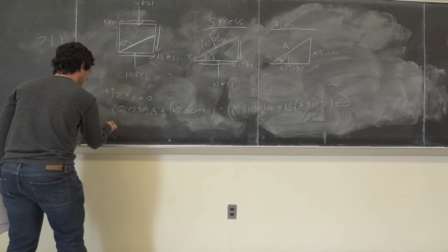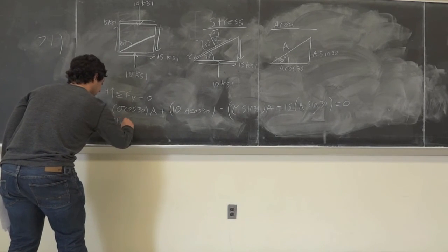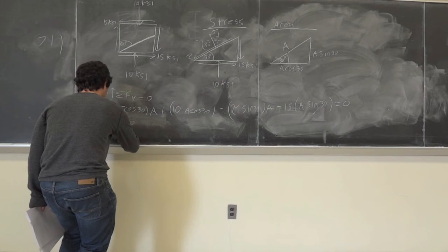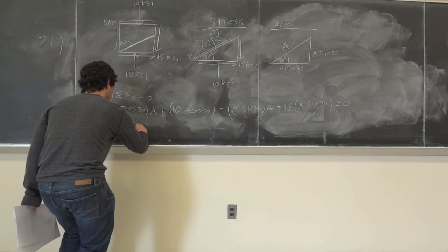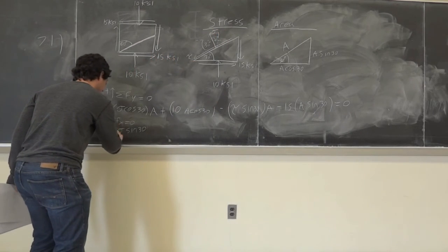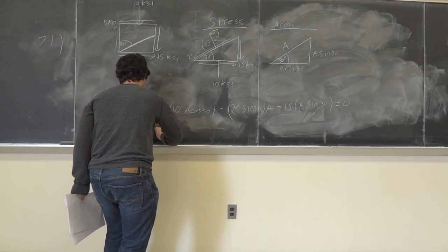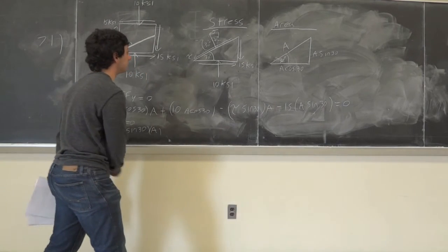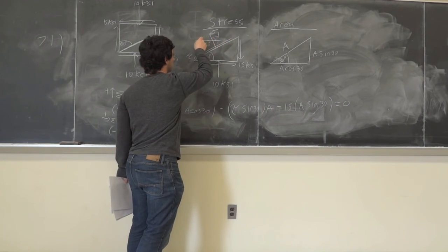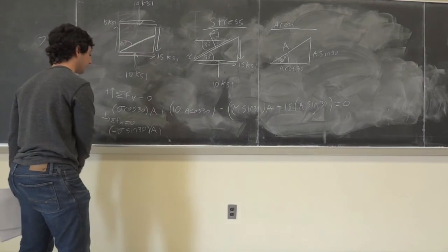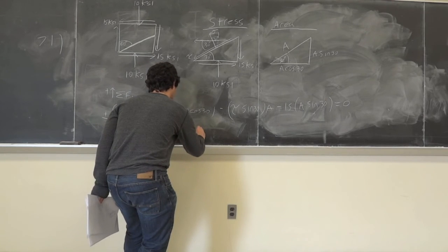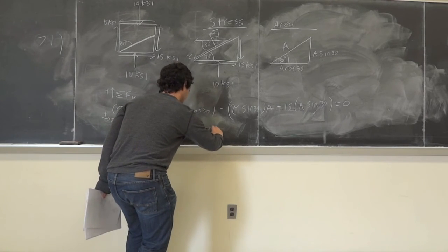So summing the forces in the x direction, taking the right to be positive, you have minus sigma sine of 30, that's this component over here, multiplied by its corresponding area, which is just A. And then you have minus tau times the cosine of 30, that's this component of the force, multiplied by its corresponding area, which is just A.